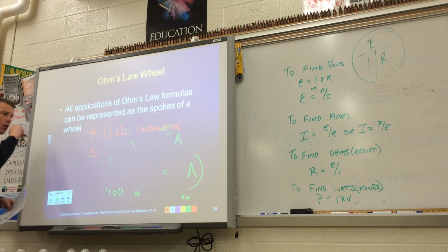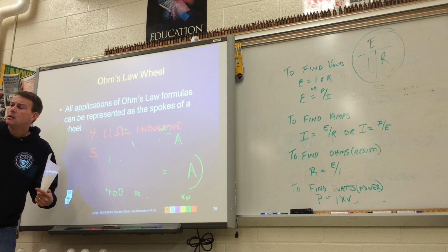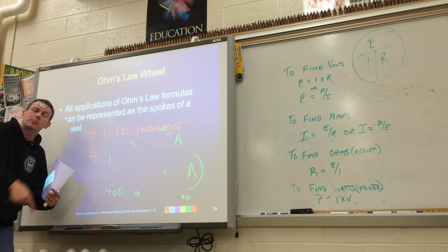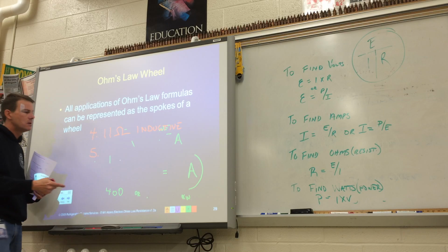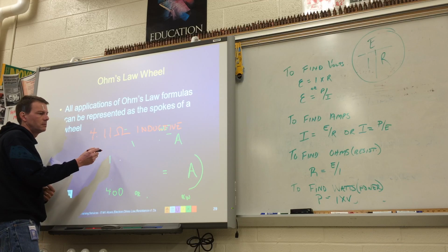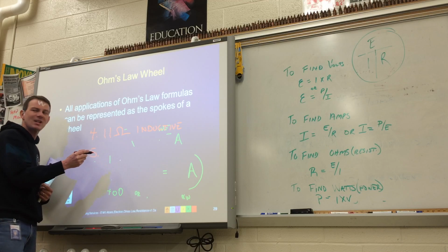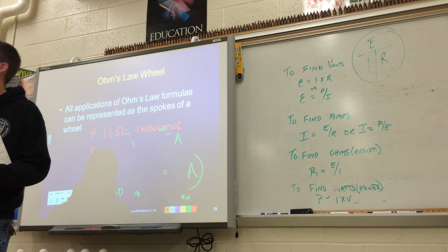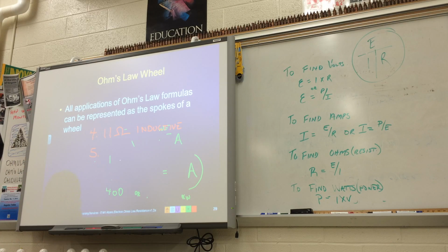The contacts, number 5. So you read the relay coil, and then you had to read across the contacts. What were across the contacts reading? Not 0. 0 is good. 0 means you got no resistance and a complete connection. Did you have 0? What does it say on the meter? No. I got 0.09. No. Should have got nothing. Should have got OL.